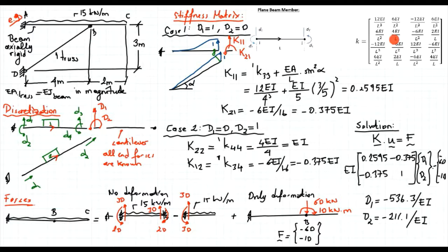After that, of course, again the same thing. You have the stiffness matrix here, you know what the end displacements are. Multiply the stiffness matrix with the end displacements of member 1, where d1, d2 will be equal to 0 in that case, and by looking at this figure, determine the fixed end forces, sum them up with the k times u, and you'll get the member end forces for the beam member. So the rest of the procedure is exactly the same. Okay, so that finalizes this question.